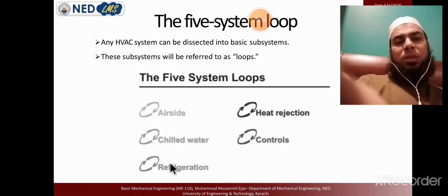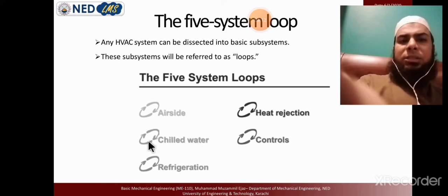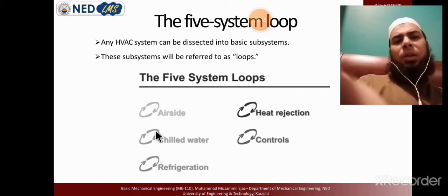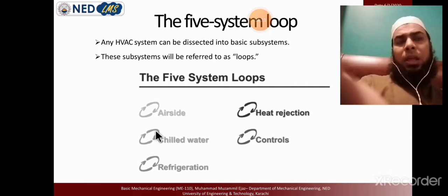Like when I was at English Biscuit Private Limited, we had 1,000 ton of chilling. So we have a 500 ton chiller, a 300 ton chiller, and a 200 ton chiller. All those chillers produce the chill water, and then the chill water is distributed to many offices and many blocks of the buildings, like the powerhouse, the production house, the mixing house, and so on.